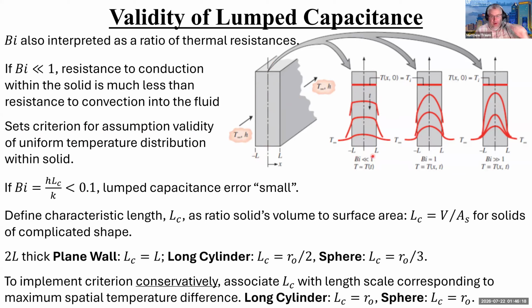And if we have our Biot number much, much less than 1, what that means is the temperature is basically uniform all the way across, right? So if we start at elevated temperature, and then we start blowing this cold gas on either side of this block, the temperature drops, and then it drops further, and then it drops further until it reaches almost uniform temperature.